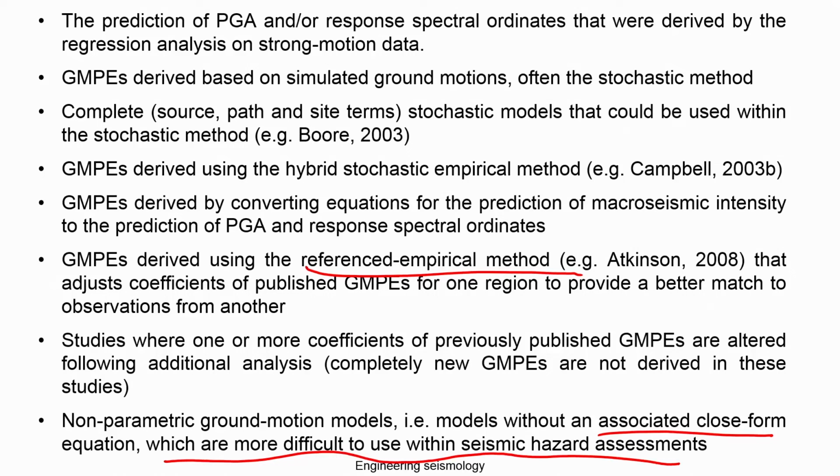Then we also developed an empirical model by combining the recorded and the simulated data, which is calibrated and adjusted for the regional seismotectonic parameters. The source and path parameters are estimated from the recorded earthquake data, and then those parameters are compiled.